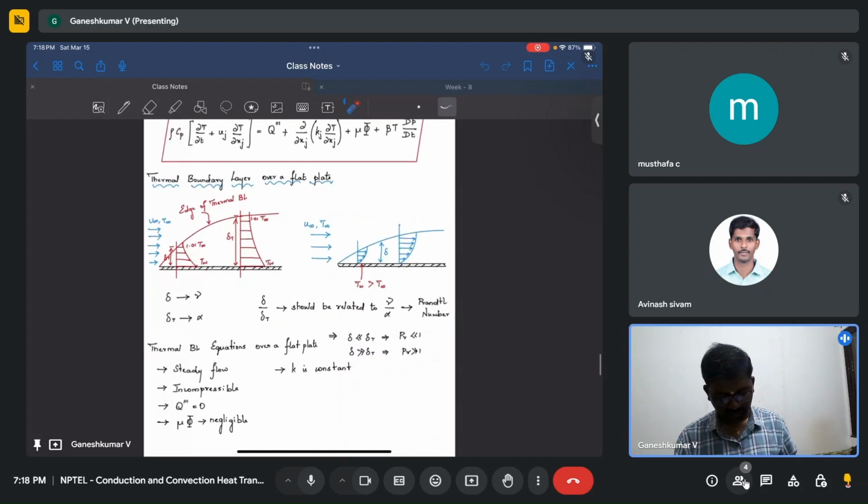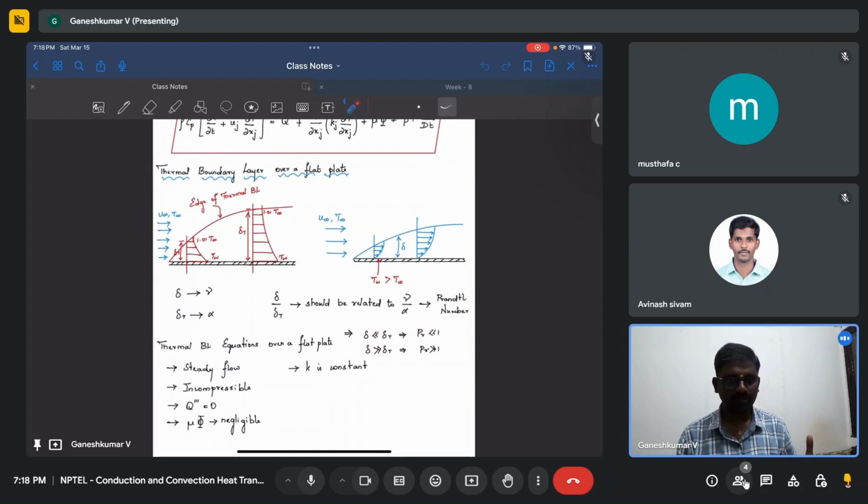So we know that there will be a boundary layer development because of the no slip boundary condition at the surface, hydrodynamic boundary layers. So when the flow is like this, it is going to see the surface. The surface is at rest, or it can move at some certain velocity, but here the surface is at rest. So the fluid adjacent to it will also be at rest. So it has to come to rest. That's the no slip condition. If you make that rest, then it starts pulling the upper layers of the fluid, and because of viscosity the momentum diffusion happens. That is what you are seeing here, boundary layer development.